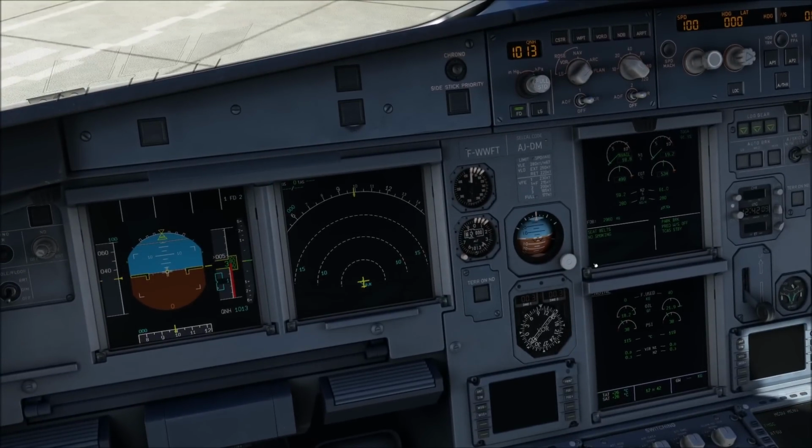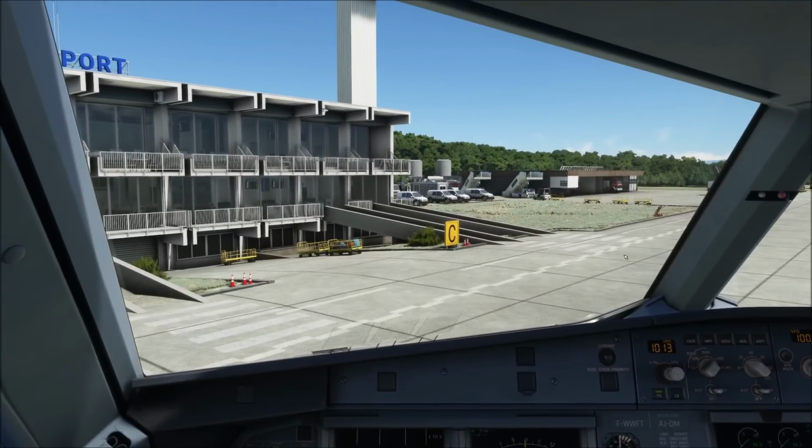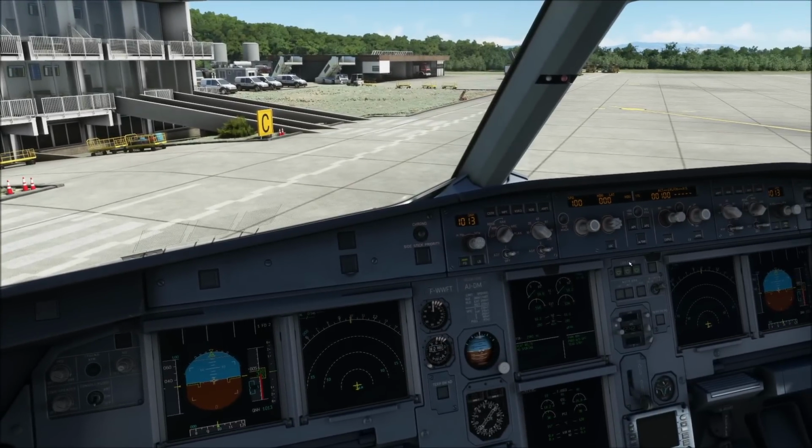Alright, that is 4 ways how to start an Airbus engine. There is a 5th. Unfortunately, I'm not able to show you that within the simulator because simply no add-on that I'm aware of actually offers that option. And that option is an engine start valve manual operation. So if you had an engine start valve fail, then the start valve can be operated manually by the ground engineers. Now, for this you will typically need an actual engineer and not just a ramp agent or your typical ground crew.